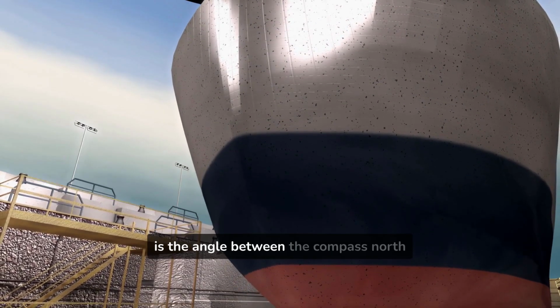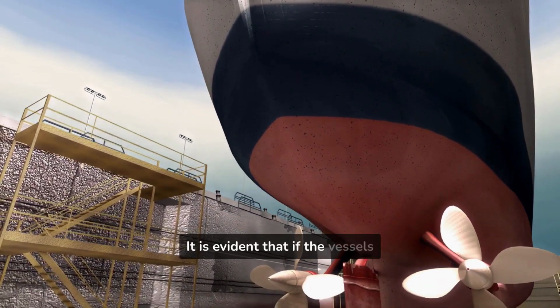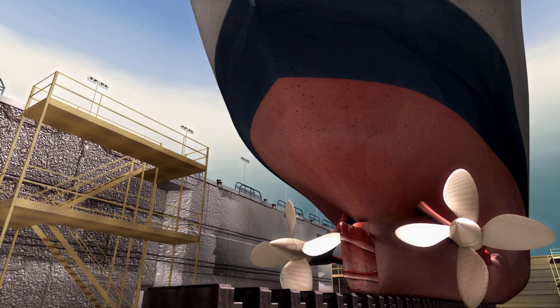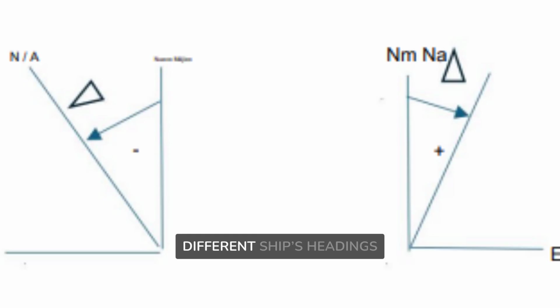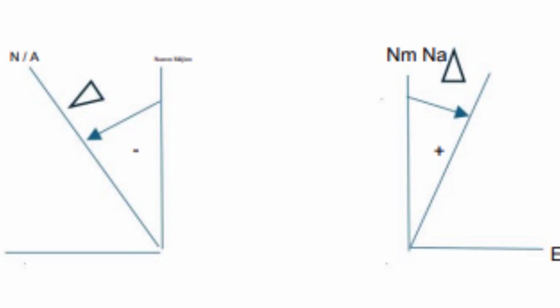Deviation is the angle between the compass north and the magnetic north. It is evident that if vessels were built with non-magnetic materials, there would not be any deviation. The goal of the adjustment is to reduce this deviation as much as possible. For the ship's different headings, there are north, magnetic, and compass meridian as reference. As a result, there are true, magnetic, and compass headings.